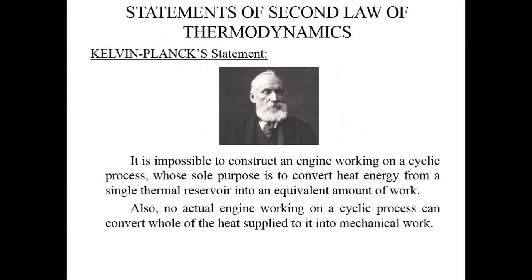Now we are going to discuss a major law of thermodynamics, the second law of thermodynamics. The second law completely governs the heat transfer phenomena. It has two statements: one is the Kelvin Planck statement, and the other is the Clausius statement. The Kelvin Planck statement says that it is impossible to construct an engine working on a cyclic process whose sole purpose is to convert the heat energy from a thermal reservoir into an equivalent amount of work.